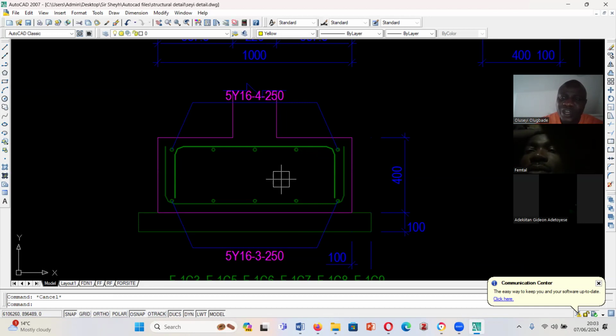it is in a way very correct, because by the time your bars are touching the soil, yes, it is going to be a problem. But the major purpose of your biscuit is to create the concrete cover below your reinforcement bars. Do you get it? Okay. So that your concrete can fill in those places.